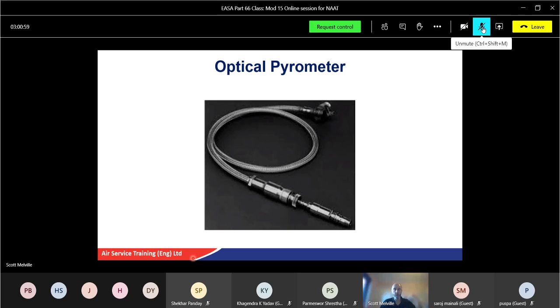Yeah. So the big hole that is facing into the gas stream and the small hole at the back of the probe. So it comes in, goes up and then out. So that's why the holes are staggered. Hence the stagnation name. And the other one's rapid response, which is quicker. Because it's going in quicker and coming out quicker, it's not as accurate. So there's positives and negatives for each type. So stagnation is slower, more accurate. The rapid response is quicker, but less accurate.